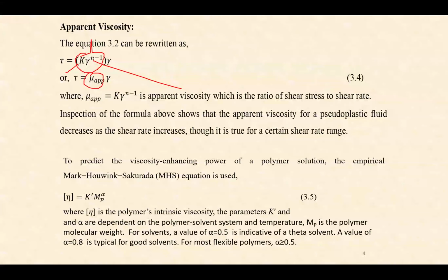And that input is sometimes required for simulation studies when you are incorporating the improvement of mobility ratio, and you have already gone through how this mobility ratio improves the areal or vertical sweep efficiency. Obviously, if the apparent viscosity or mobility ratio is less than 1, then your sweep efficiency will be significantly higher.